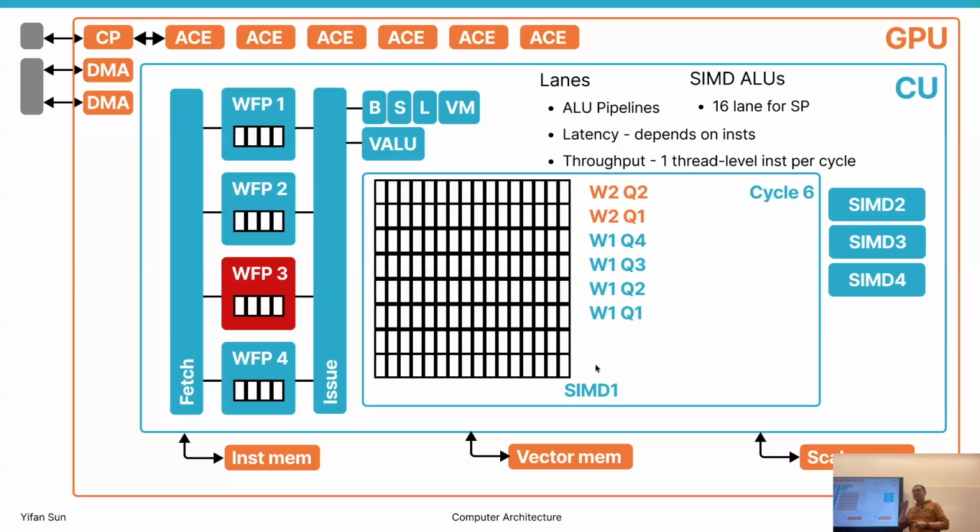They can just calculate how many pixels they need to calculate per cycle. Then they need to know how many vertices they need to calculate per cycle. Then they just go backward and calculate every stage: I want this thing to output 16 values per cycle. Then for every compute task, we need to load this amount of memory. Say for every compute, we need to load 4 bytes of memory. Then we need to design the vector memory with that particular bandwidth.